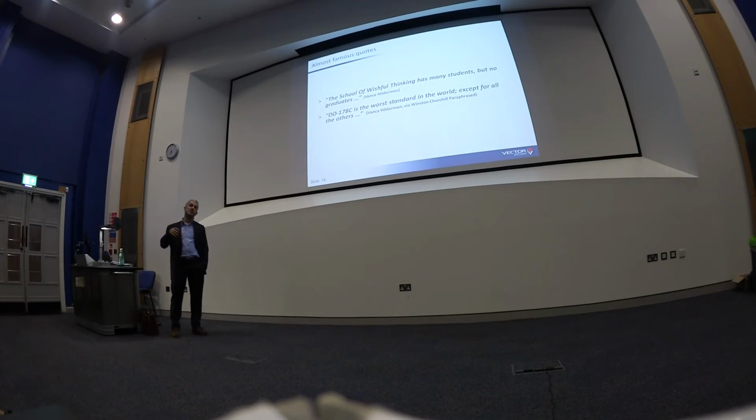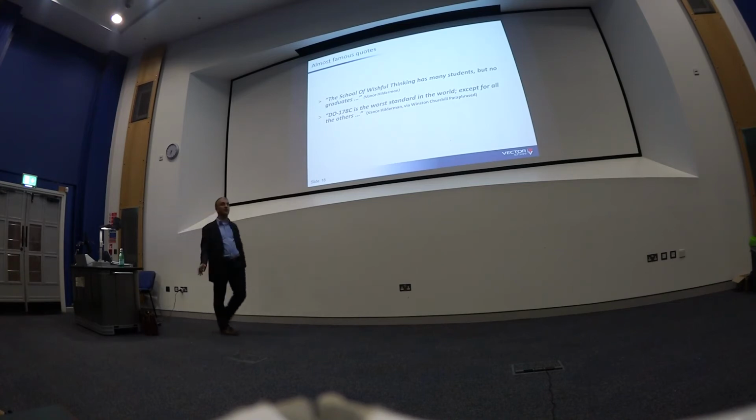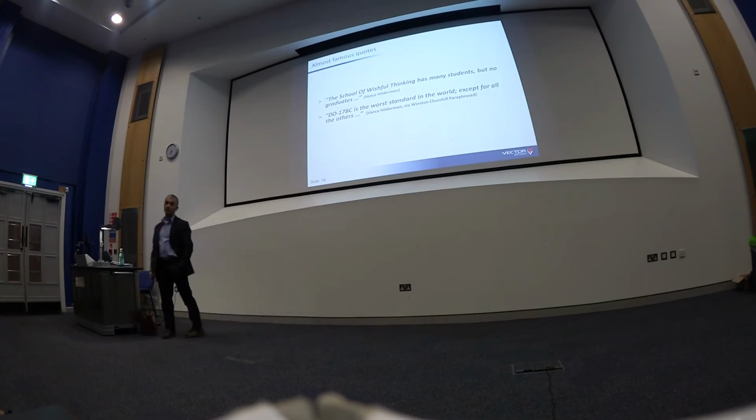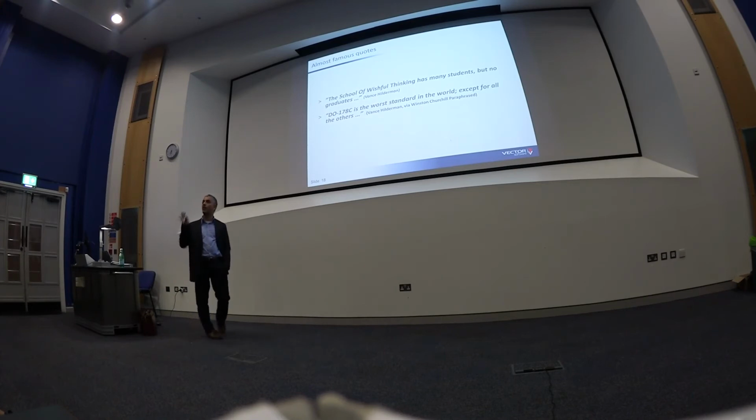For software, it's not possible to do this kind of calculation. It's completely impossible. Over a few hundred lines of code, it's impossible to calculate if there are errors, and it's impossible to calculate an MTBF or a similar value. There is a probability of failure. The FAA, the Federal Aviation Administration, is very clear about this. What is the probability of a software failure? It's very simple. 100%. It's easy. The software will fail, and you have to be prepared for this.